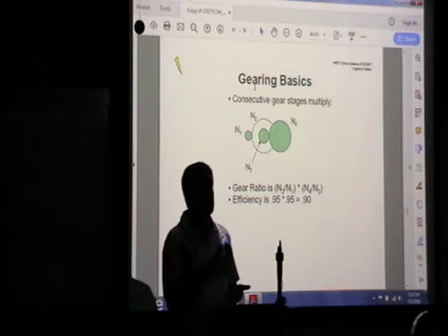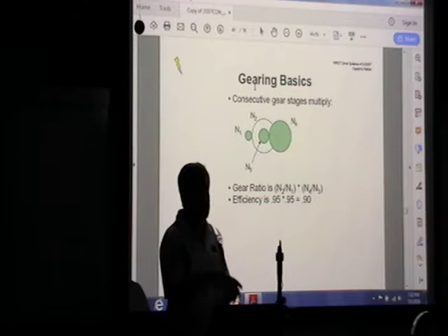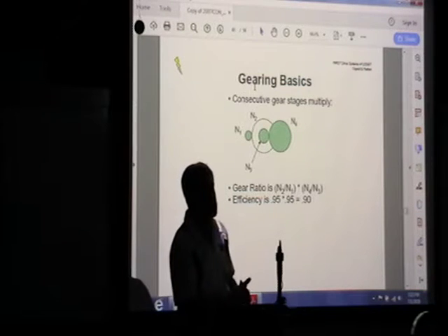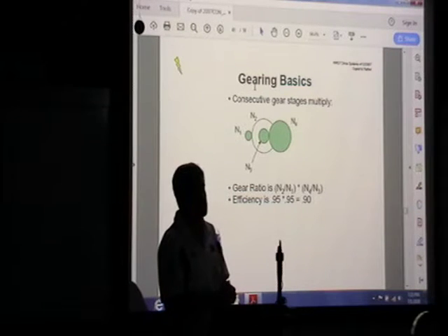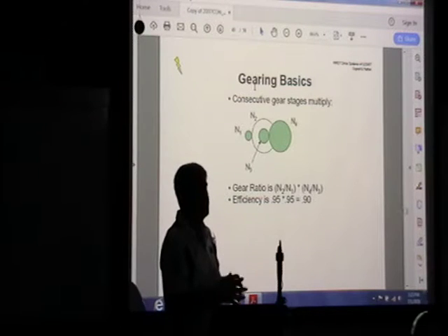There again, gearing is in there so that you can get your mechanism to work. You've got to start that load moving, and you want to keep it running at your maximum efficiency or power of that motor. So you're going to choose these gear sets so that your mechanism can work with that motor.